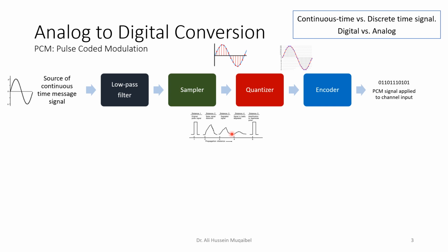Okay, so the channel is not ideal. With digital, usually there is something called repeaters. Before I lose the signal completely, I'm going to repeat the signal, recover the signal. So if you like, we can even send, for example, a positive pulse or negative pulse to represent 1 and 0. Before losing the signal, here we still can say whether it's positive or negative. But if we wait longer, we might lose this. So we use a repeater to repeat the signal exactly as it used to be.